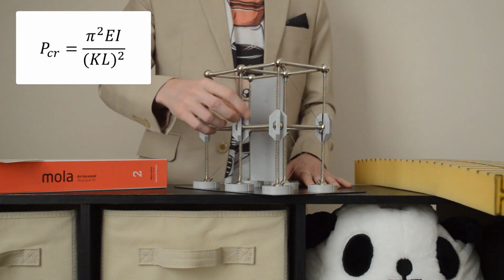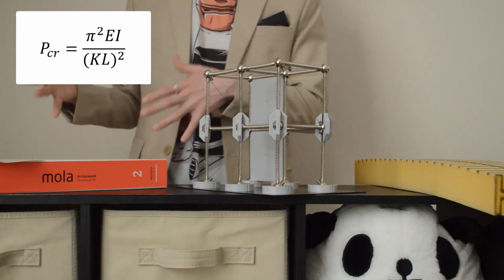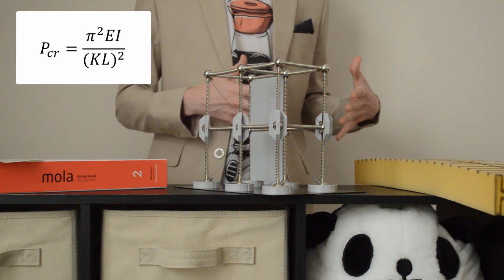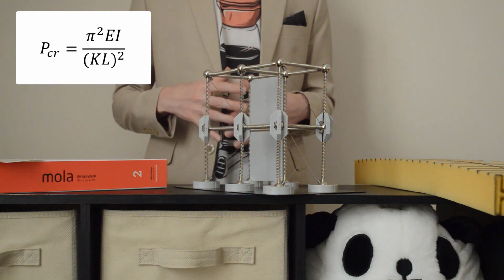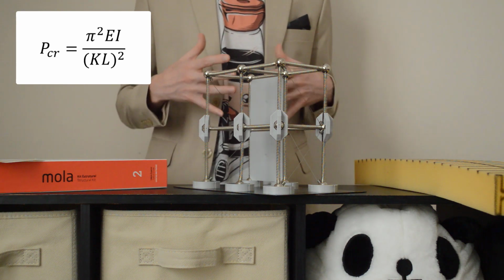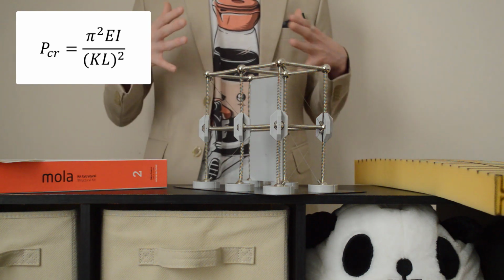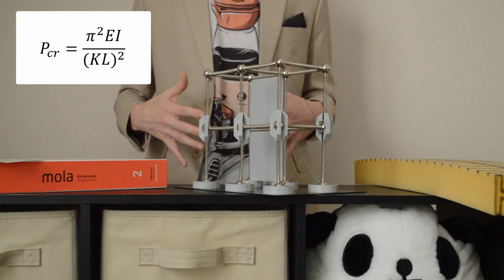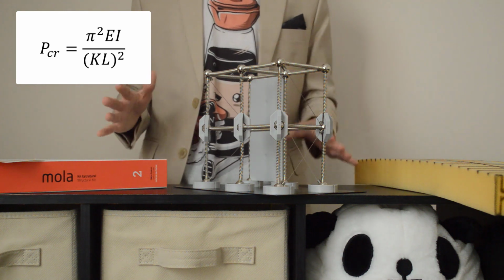You may think that by removing floor area near a column, you are removing load from that column and therefore removing demand and making that column's life easier. But you may also be removing bracing for that column and significantly increasing its unsupported length and therefore decreasing its capacity, which would obviously make the life of that column much more difficult.